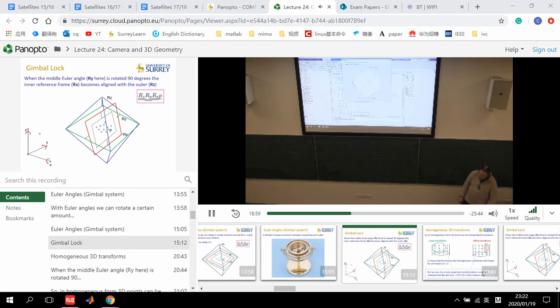Okay? Now, as I say, what we're going to do is show that if I take this theta y and change it to be 90 degrees, or pi over 2 radians, because MATLAB works in radians, then if I run this, you can see that we're rotating now about the z-axis, as we would expect, by attaching our t to the z-axis.